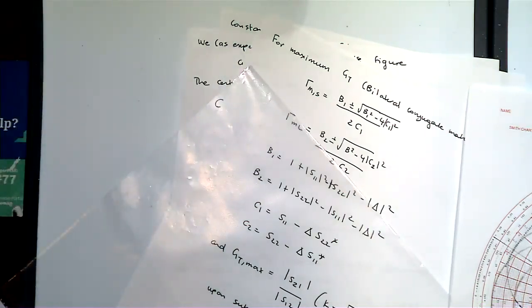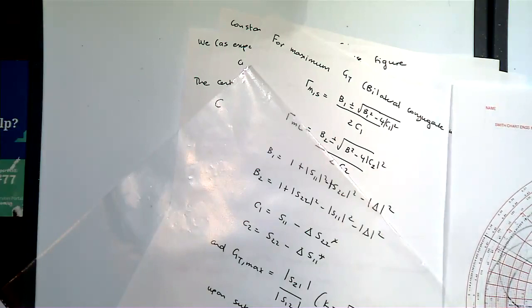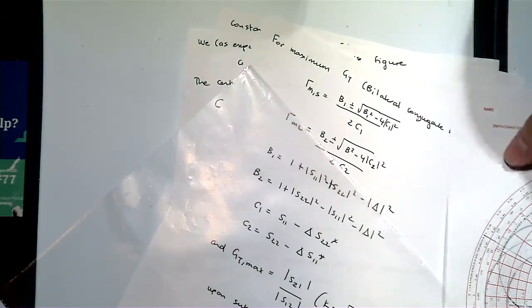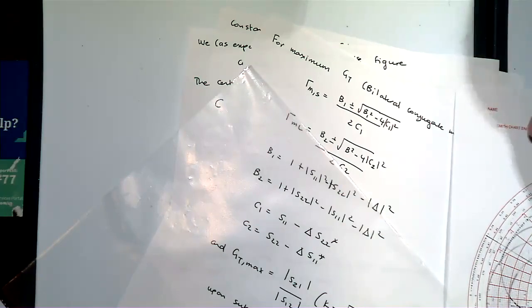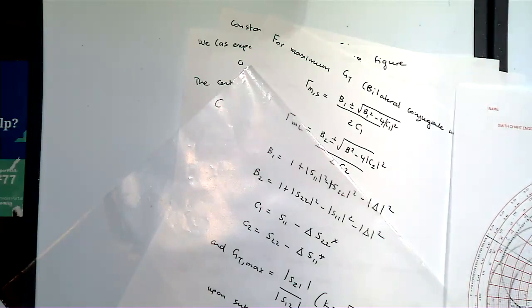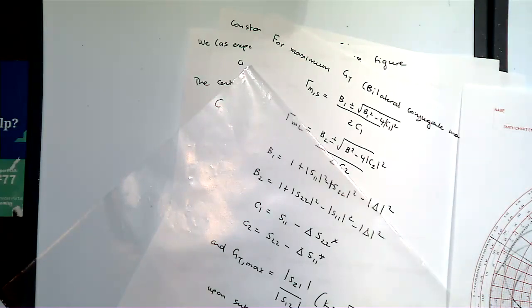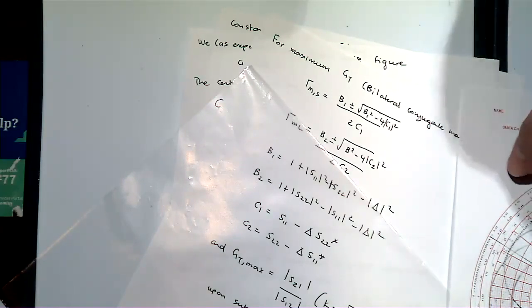So I'm starting here, and I want to get to here. Usually, we've got this impedance, how do I get there? Here I'm saying I'm here because it's 50 ohms. How do I get there? So that's why we first have the shunt and then have the series element to go up there. Usually these components should be opposite. I mean, we're in the 1 plus j.